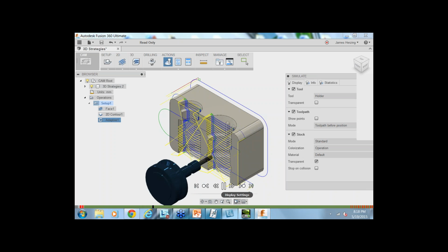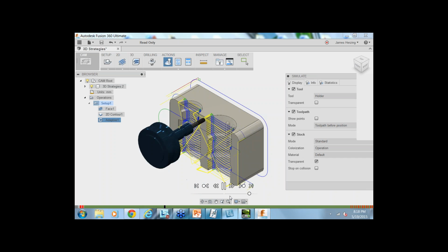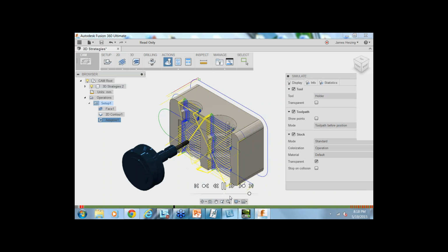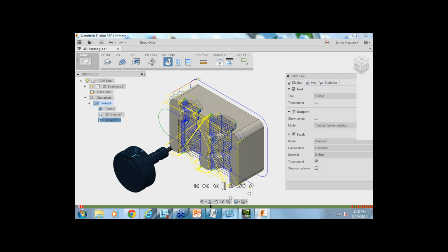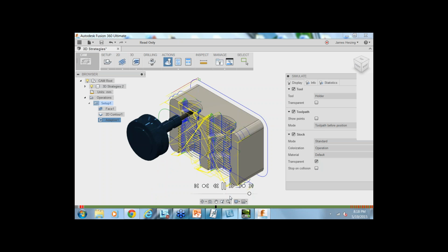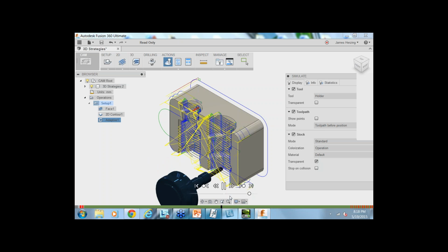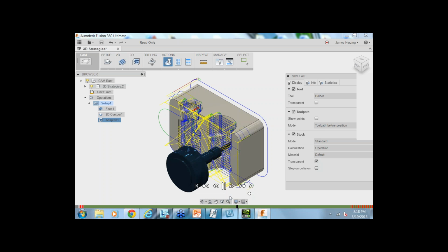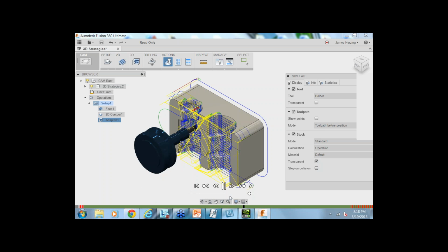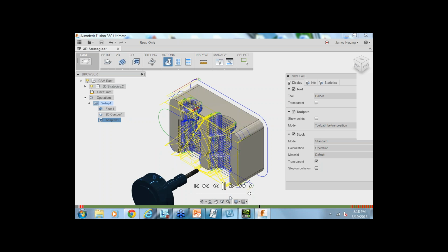That's pretty fun. So we won't watch it every time, but I just want to show you that it's a little bit different than what we were doing last time when it was just removing a little bit of material and drilling straight down. This one is, I would say, significantly more complicated than what we were doing last week. Now, looking at something like this, how long would something like this take in the real world? Is this, oh, that's not so bad, or is it, well, you're going to break your tool, you're going to wear it down, you're going to take forever to do this? So 6mm ball mill, and you're running at about 20 meters a minute at about, I think, 20,000 RPM.